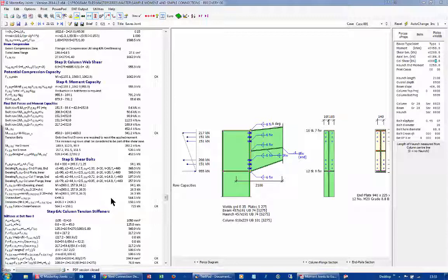In the BS, we took the applied tension over the capacity plus the applied shear over the capacity and had a 1.4 unity value on the combined. Well, in the EuroCode, the 1.4 is dragged inside the left-hand side of the formula, so it's only the tension that has a 1.4 on. That does modify the overall value to 0.28 instead of 0.4, and thus you have a 20 or 30% nearly reduction in a capacity of tension bolts, which is a pretty nice one.